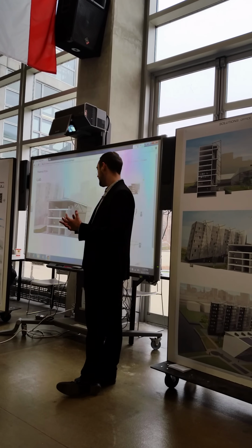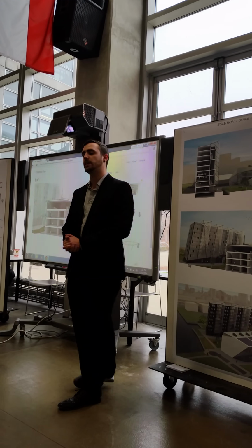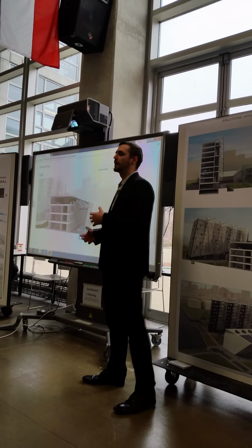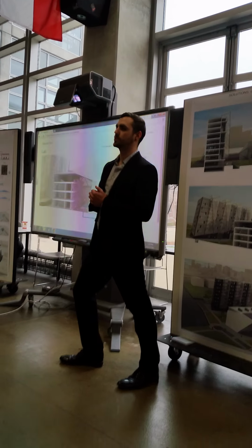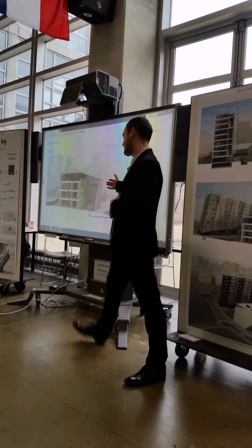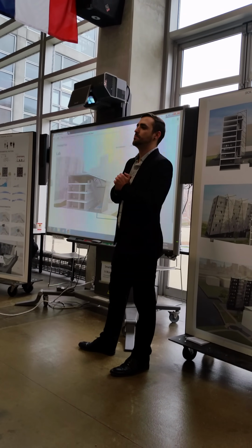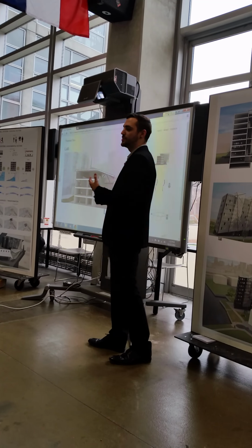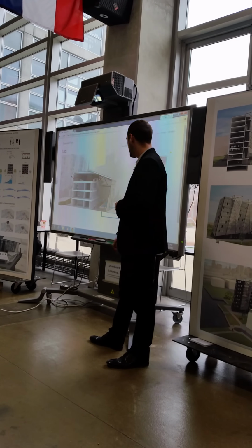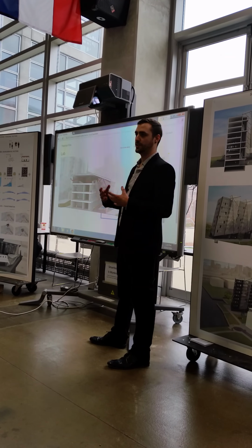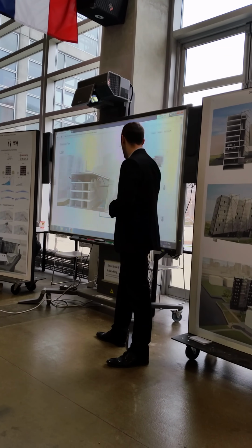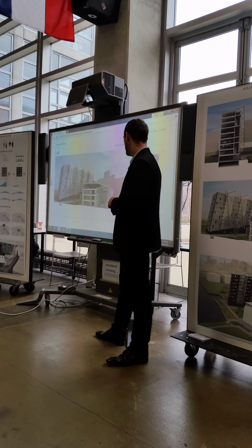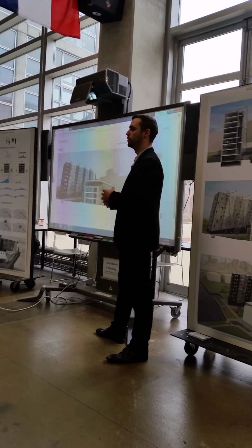In the summer, we get more heat, solar radiation, these coils can expand. We can use the storm water that is being collected from the surrounding site in these biofiltration systems or pools to add to the dehumidification of some of these spaces. We can open hatches in these ETFE coils and allow natural ventilation into the space to cool it naturally instead of relying on large air conditioning units. And then a whole system working together to heat and cool this building.